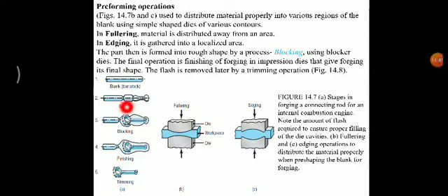and because of which we can get the part in step 2. The third process is the blocking process. Blocking is simply like a forging process. The forging die will come, we have to keep this part in the forging die, then we apply the forging force in the particular designed die, then further it will get finished to this size by removing some of its material.